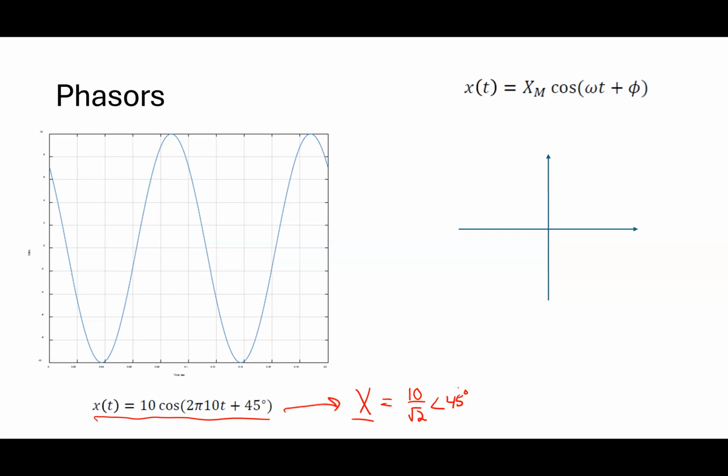What's the voltage coming out of that wall socket right there? 120. What is that, RMS or peak? It's RMS. We talk of everything in terms of RMS, root mean squared. The peak value of that voltage should be about 169 volts, right? Really it's 120 RMS.